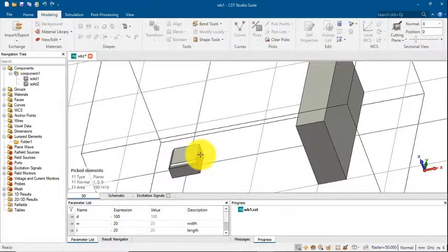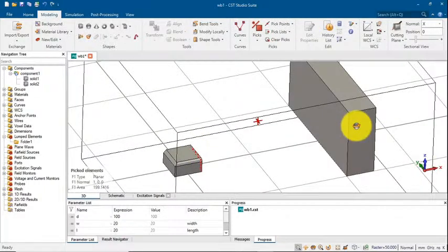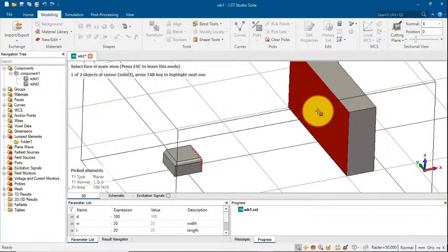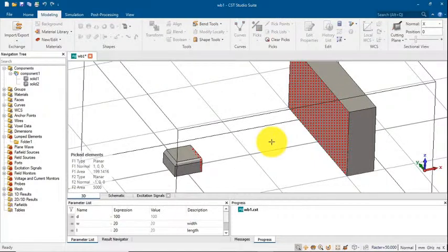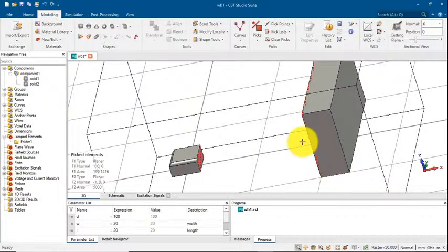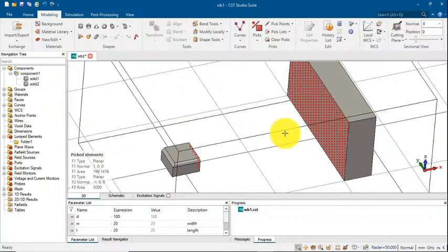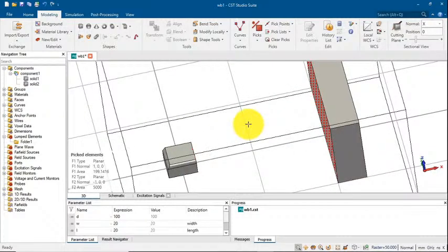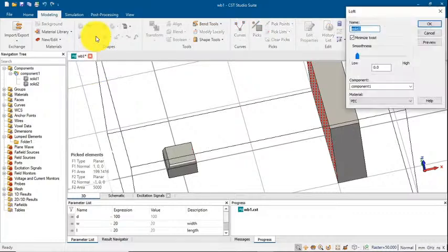Then you will go to this way and press F also to pick it. Okay? We have these two faces because we want to connect them. But how can we connect them? We will go and use this one, the loft. Connect two picked faces. Okay? Two picked faces. And this way we can connect them. How? We can press preview.